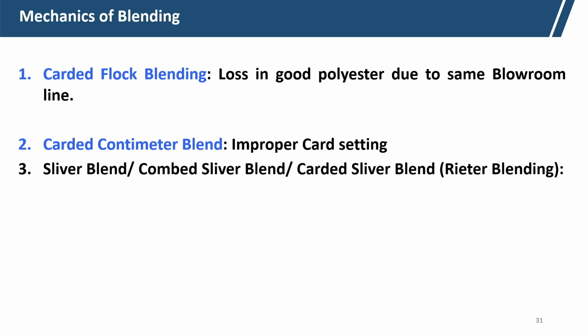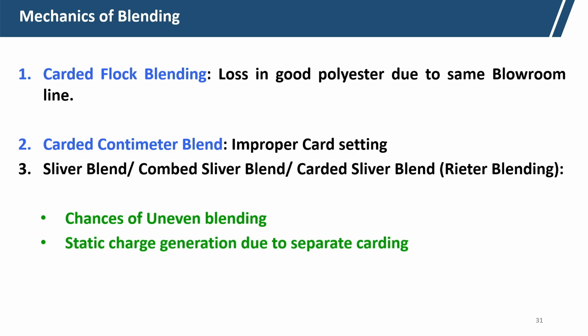In sliver blend, combed sliver blend and card sliver blend, the retard blending, the chances of uneven blending are there, definitely, that I have discussed. Static charge generation due to separate carding. Because polyester is carded separately and cotton is carded separately, polyester generates a static charge.